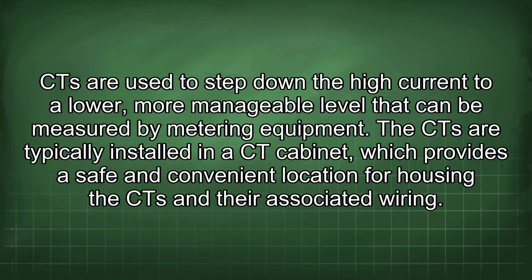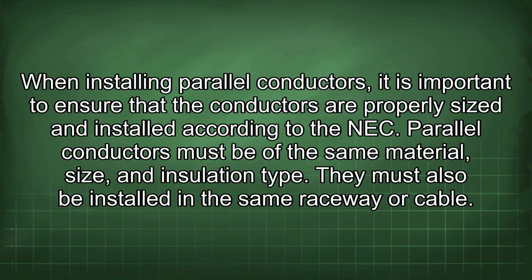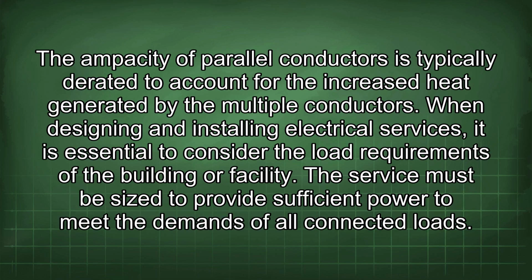When installing parallel conductors, it is important to ensure that the conductors are properly sized and installed according to the NEC. Parallel conductors must be of the same material, size, and insulation type. They must also be installed in the same raceway or cable. The ampacity of parallel conductors is typically derated to account for the increased heat generated by the multiple conductors.